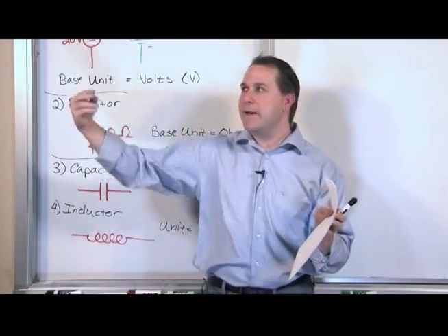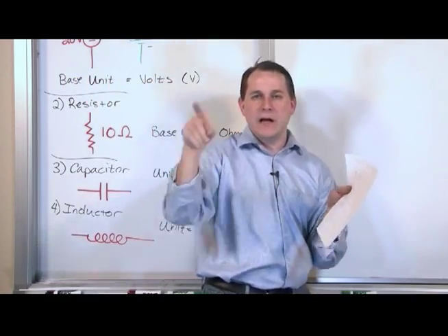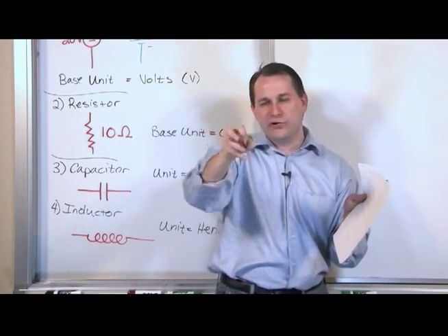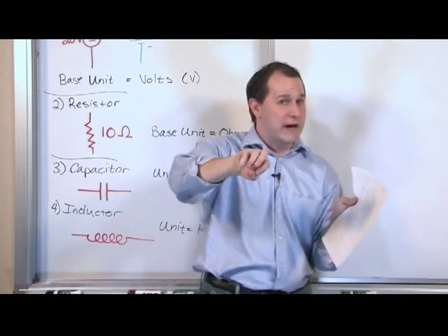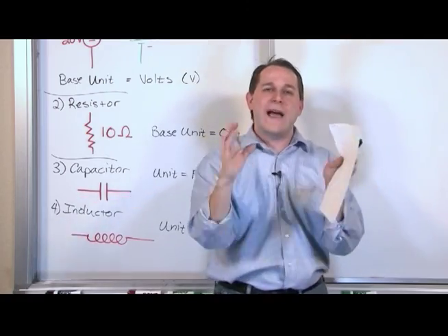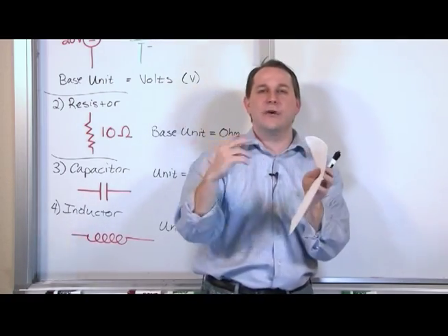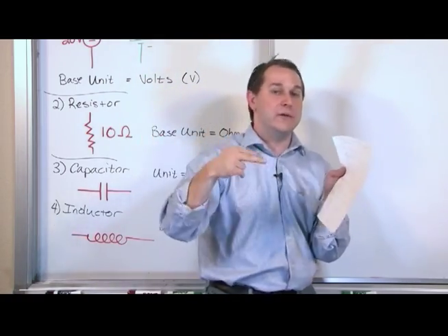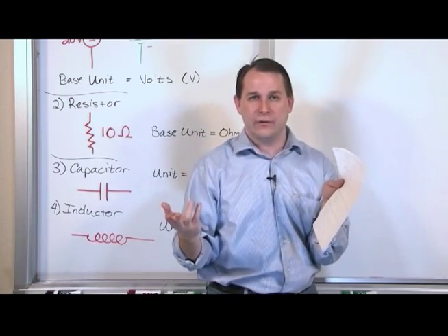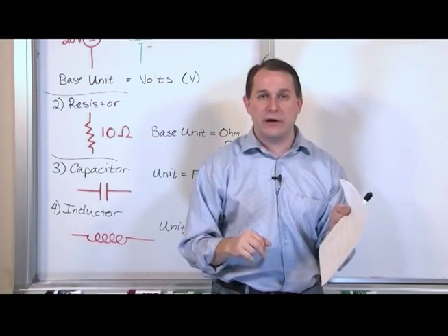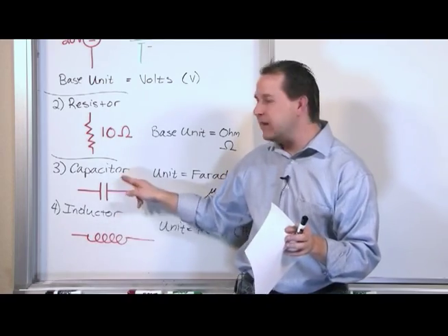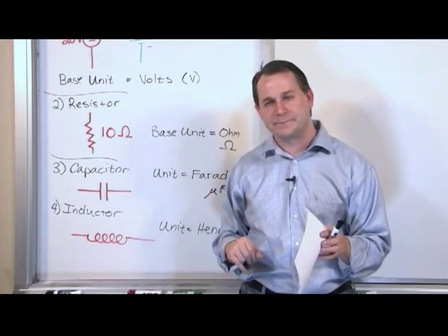So it's kind of like you can think about the wave comes in, hits the antenna, and goes to these capacitors and inductances. Of course, you can tune the knob and change the value of this capacitance, and when you do that, you're changing the way the circuit behaves so that that frequency that you want, the radio station you want to listen to, is the one that gets sent to the speaker because of this perfect dance of energy between the capacitor and inductor.